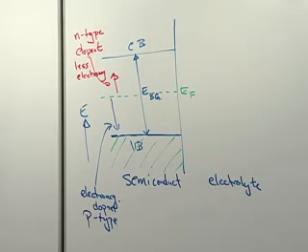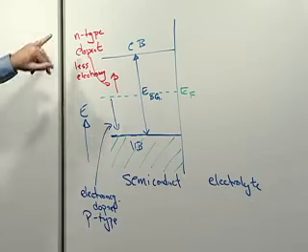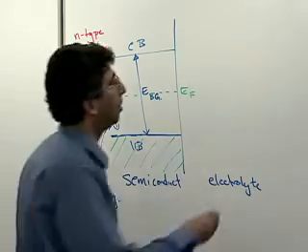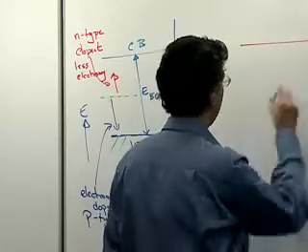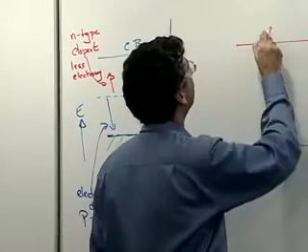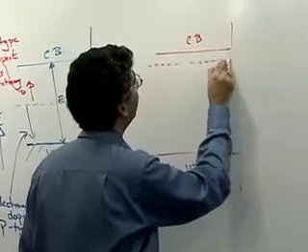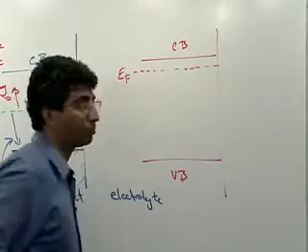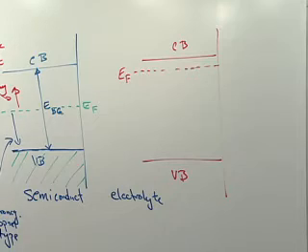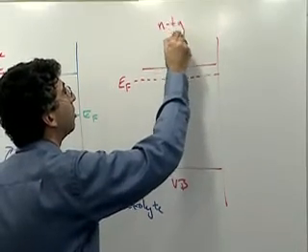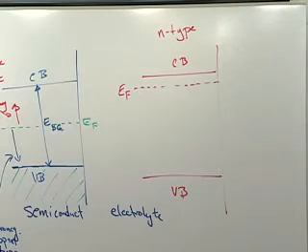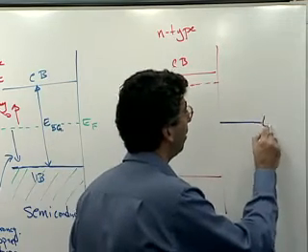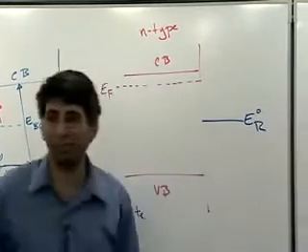So I have time in the next few minutes to consider just one case. I will consider the case of an N-type dopant. So now we have our semiconductor, we have our band edges, and we have our Fermi level that's up here somewhere near the conduction band edge, because we have picked an N-type semiconductor. It's in an electrolyte. That electrolyte has a redox potential, probably not the same as the Fermi level, so let me just put it right there arbitrarily, somewhere else.